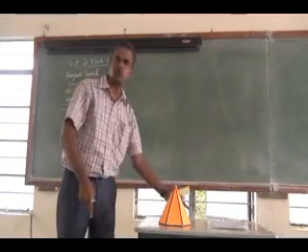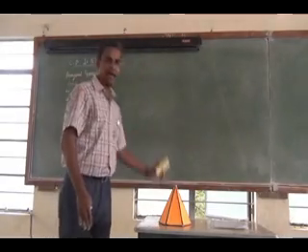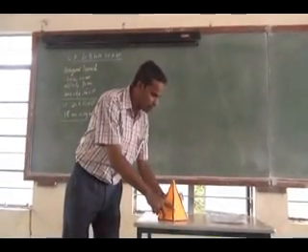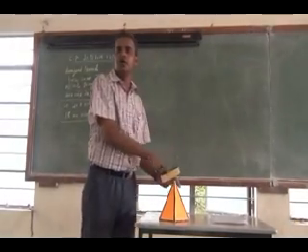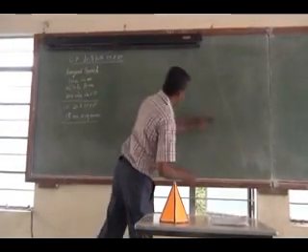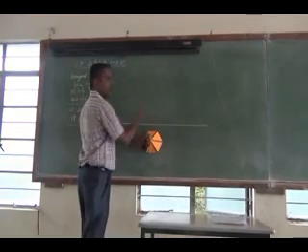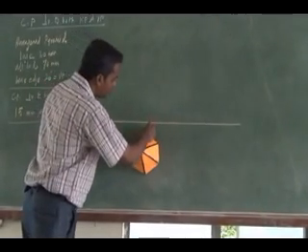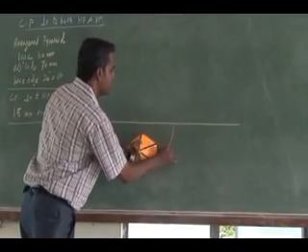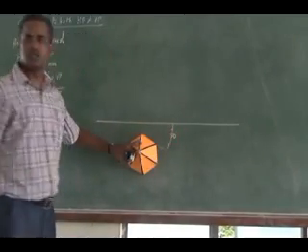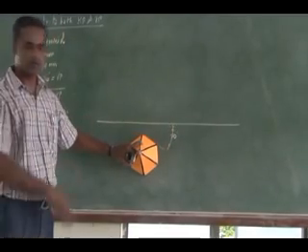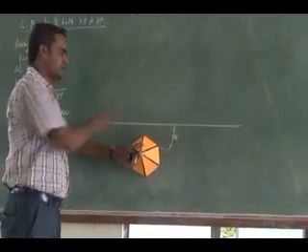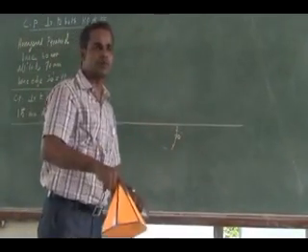So see here, in this orientation, one base edge is parallel. So what is given here? It is 20 degree inclined. So I can make that edge 20 degree inclined, and then I can draw it. So now the edge is 20 degree inclined, so I will make it 20 degree. This is how you have to draw your hexagon. So you draw the hexagon, proceed for the front view, then proceed for the left side view. Do it. Draw the projection quickly.